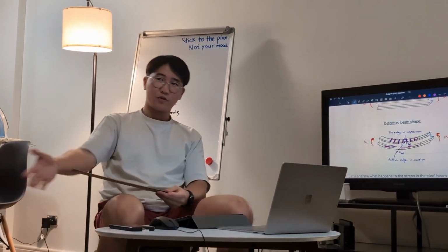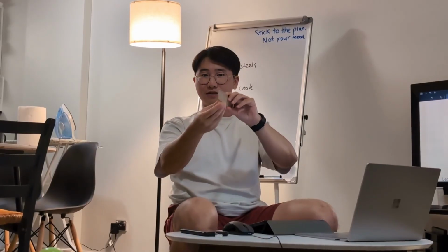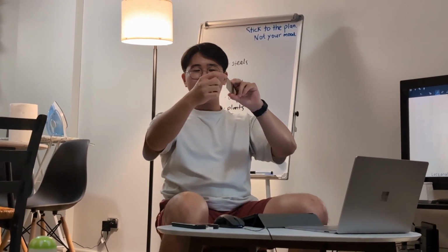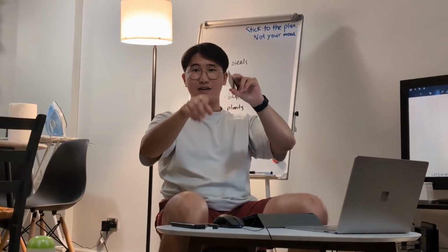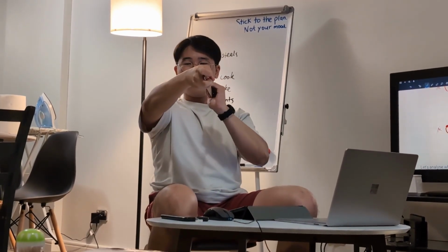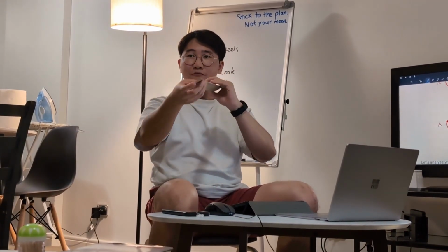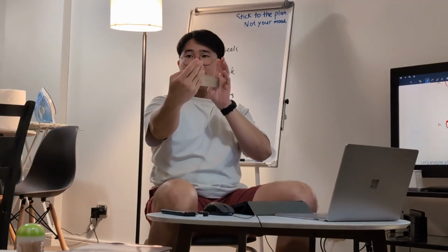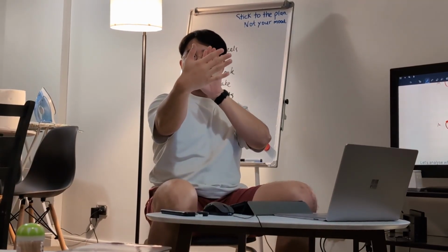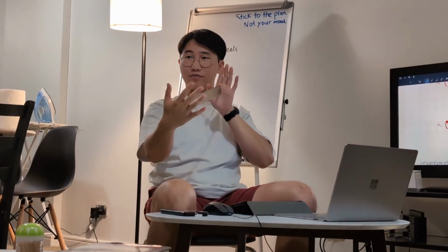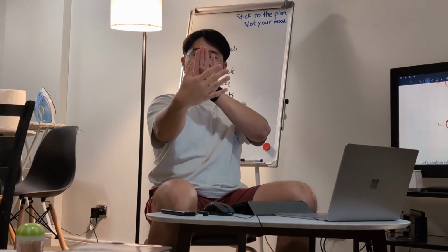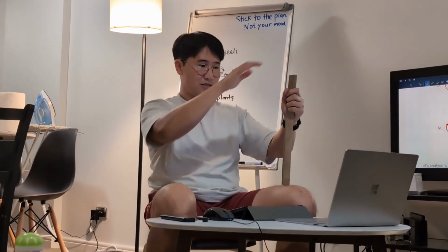So, okay. Rewinding to compression, right? In compression, we have our major axis and our minor axis. Do you remember the major and minor axis? Basically, the major axis bending is kind of this way. So if I try to put loads on it, like down like this, that's going to be the stronger direction, that's going to be the weaker direction. So that's the minor axis, right? And then what happens is, for this shape, we get this buckling, Euler buckling effect, right? Remember, that's in compression. Because what I'm doing is pushing the column, it's going to buckle against the minor axis.